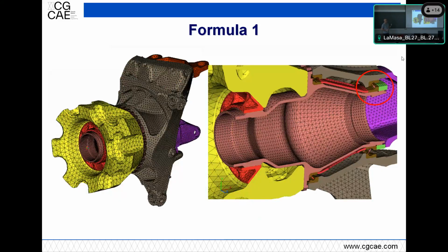But if you are below the minimum weight, you can put ballast wherever you want. So the lighter the car is with respect to the regulations, the more ballast you can add, and you can put this ballast in front, at the center, on the rear to balance the car. So this is the real stuff in having a light car, because, as I said, regulations, you have to fulfill a minimum weight.